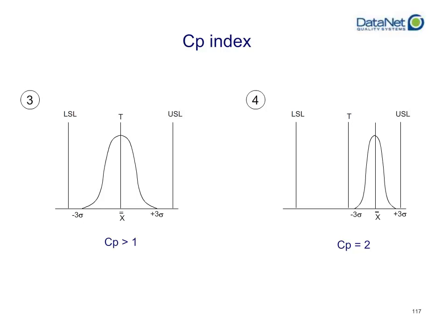Now you may notice on this particular slide number 4, unlike the other 3 slides we saw previously, there's something that should be glaringly obvious as a problem here. You could theoretically be producing twice as much good product if your CP is 2 than if your CP was 1. However, that doesn't necessarily mean you're producing within specs, or that you're not close to starting to produce data that's out of spec.